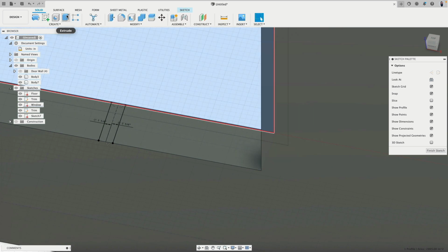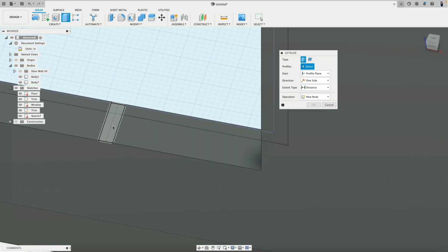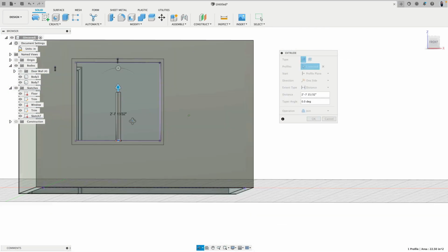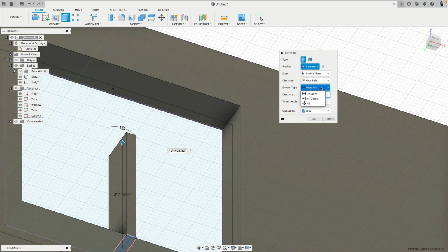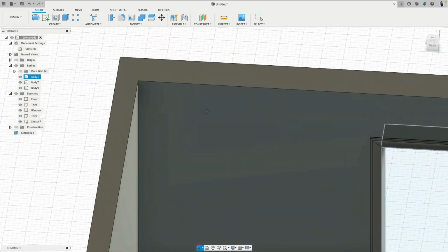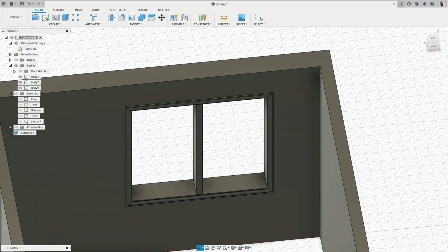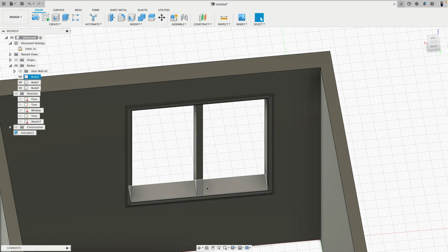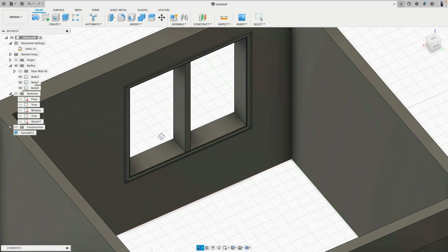And then I can go to Solid, go to Extrude. I need to show the sketch here. The sketch, I extrude up. And to hit this face, I say for the distance to the object, this one, as a new body. There we are. Easy peasy. Now, there we have kind of like this centerpiece created. Now, these two elements here are very much the same. So the question now is, how do we model actually the rest that goes in there?